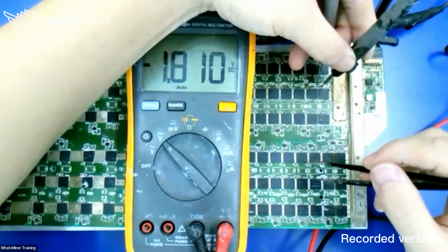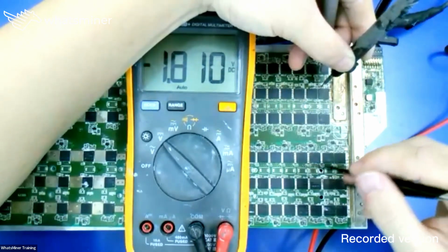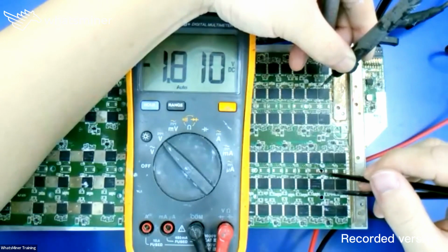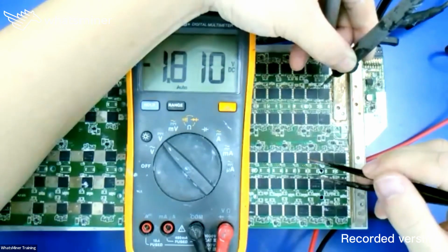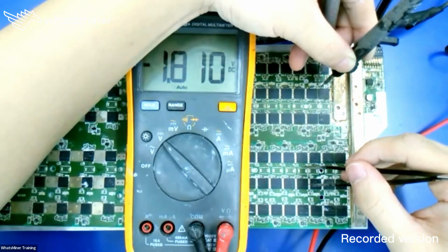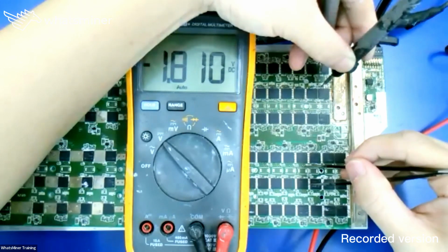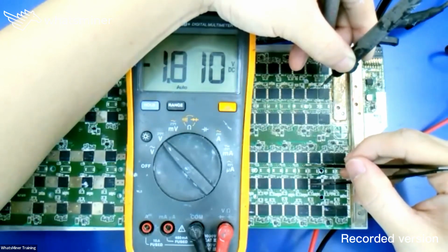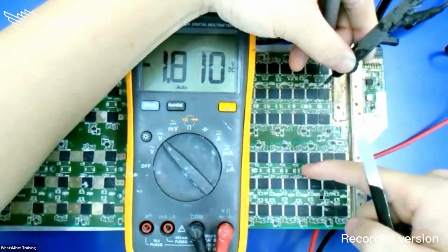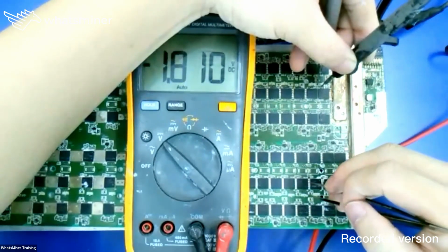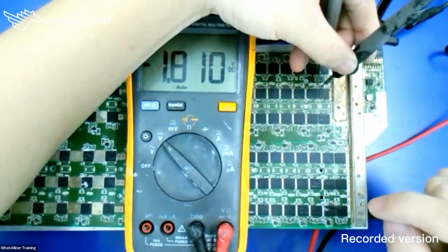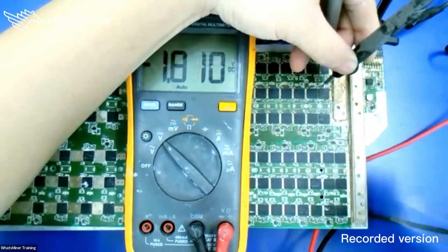Use this method to narrow down the area you need to check. Repeat several times, and you can judge which one is the defective one. At that chip, you short the RxD at the input test point of RxD. If it can fall to 0, that means normal. And then you short it at the output, and you find it can't fall to 0. That means this chip is a defective one.